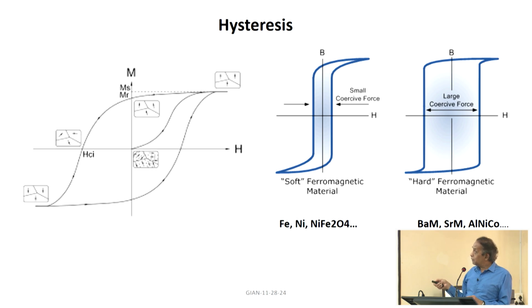Then you go back and the magnetization will decrease, but when you hit 0 field, it does not quite go to 0, because some of the domains are left with partial orientation parallel to each other. So, there is a non-zero magnetization when you go to 0 external field, and that is what is called the remnant magnetization. So, there is saturation magnetization when all the domains are aligned parallel, and then when you go back to 0 field, the leftover magnetic moment is called remnant magnetization.